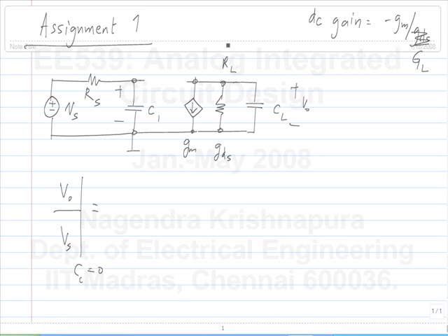So in this case it's very easy because the two poles are separated. You have the transfer function of the first part. What is this from Vs to this point? And what's the transfer function between this voltage and the output? So this is basically the current of Gm times this Vg or Vx will flow here, and that flows through the parallel combination.